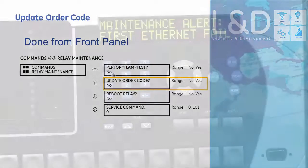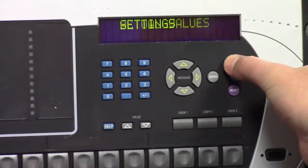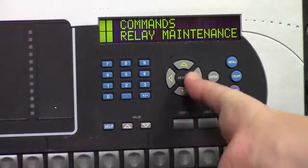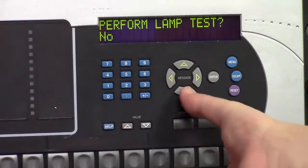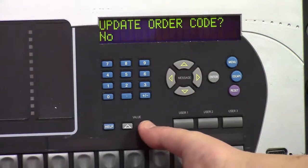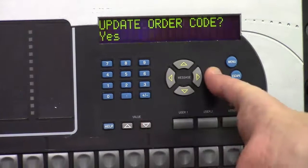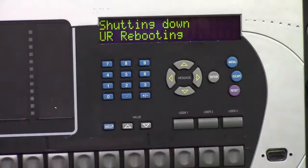So let's go ahead and do this. From the front of the relay, we'll press the menu button until we get to commands. First thing we'll see is relay maintenance. We're going to go to the right. The first thing we see is perform lamp test. No, we're going to go message down. Update order code. Use the value key to change it from no to yes, and press enter. The relay will now go through the reboot sequence. It's going to evaluate everything that's in the chassis and update its internal order code. Now, one thing to keep in mind, when this occurs, you're going to lose all the settings in the relay.